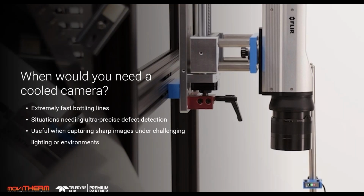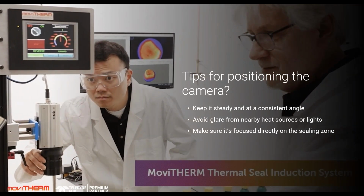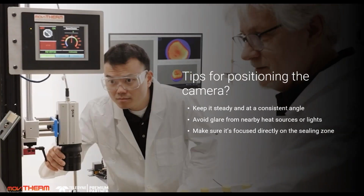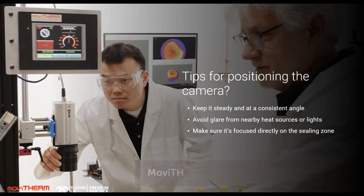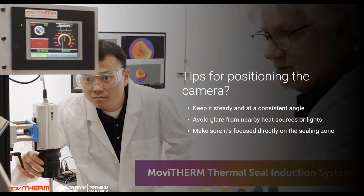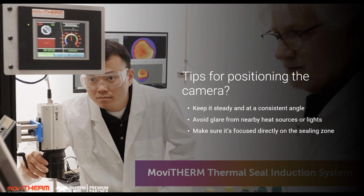So when we do this evaluation, we let the customer know exactly where to position it. Now there's some flexibility there, within 6 to 10 inches or so, but we'll identify exactly where you need to mount the uncooled camera. With the cooled camera, not as important. We can pretty much have that mounted right over the cap immediately after it comes through the induction sealer.